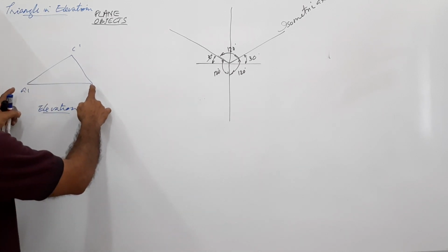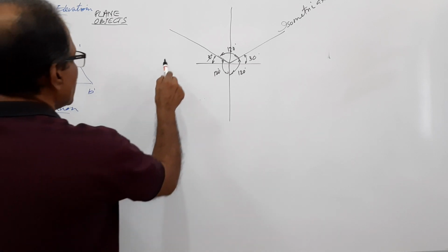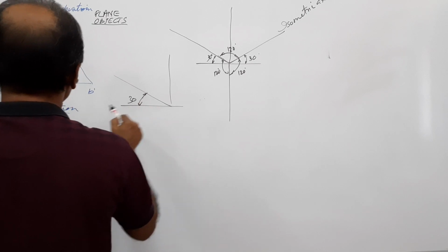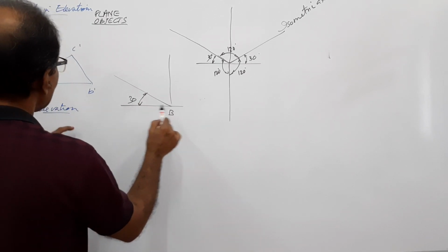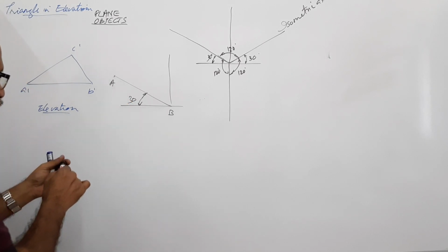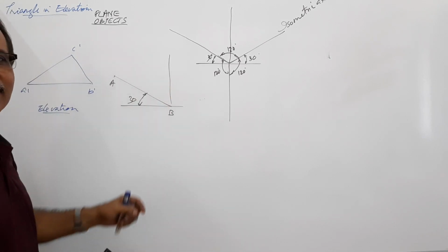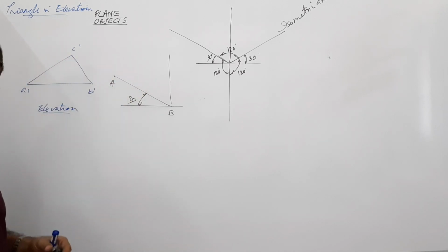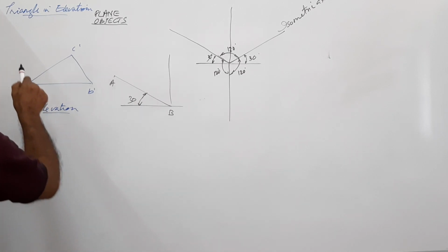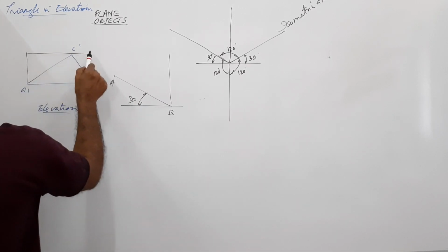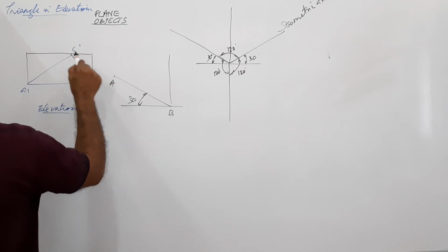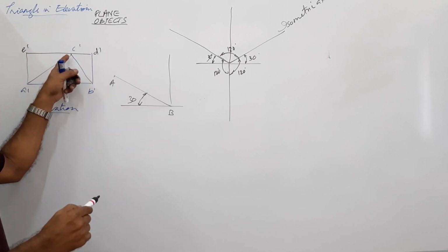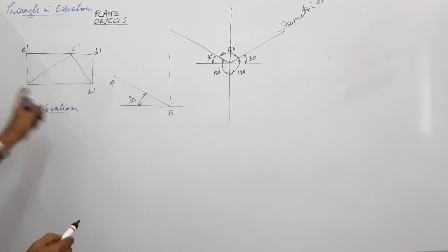You know this length. If you draw the two axes, I draw this vertical axis, this 30-degree axis. I can choose B here, I can choose A here. Now, this BC is not BC here because this is not along the axis. This AC cannot be taken there because it is not along an axis. So what do you do? You inscribe this in a rectangle. Which rectangle? Some rectangle, A dash, B dash, D dash, E dash, so that one side of the rectangle passes through C dash. Agreed? Reproduce the rectangle here.